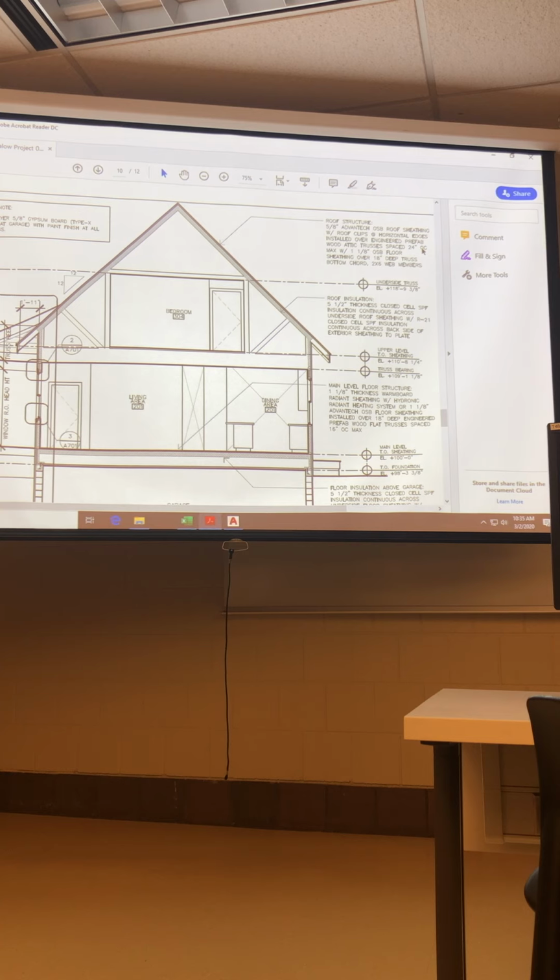Okay, what about our truss spacing? The spans are bigger, yeah. Because most floor framing, we're at 16 inches on center or less. Here, because these are roof trusses, they're spaced at 2 feet on center. So 3/4 inch thick floor sheathing can't span, it's not rated to span 2 feet. It's going to be spongy, and it's not going to have the strength that we need for that span.